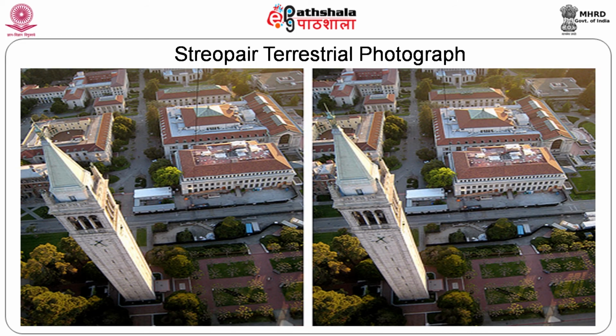Now, coming to how a stereo pair of a terrestrial area in terrain is taken: two photographs are taken, each with an overlap. I told you earlier itself, overlap will be there. When I look at this through a mirror stereoscope, as we call it, that will give you a 3 dimension, which is not possible with a single photograph. You will have to have two sets of photographs.